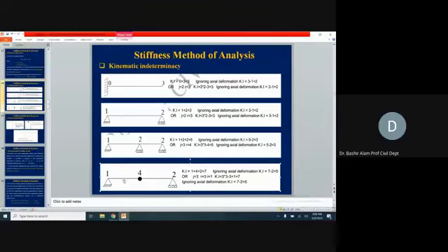And for the right hand side, it will be this vertical divided by this horizontal. Now, vertical is the same, but the horizontal distances are different. So the rotation of the left member will be different from the rotation of the right side member. And that is why we have 2 unknown rotations at the support.